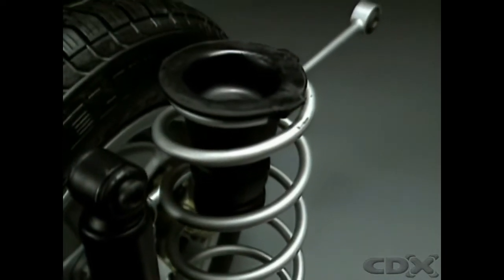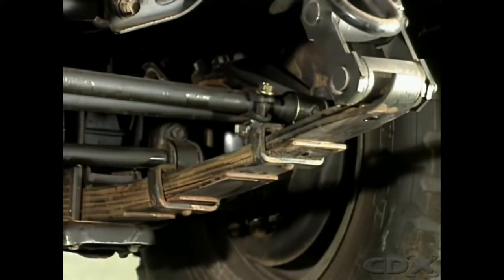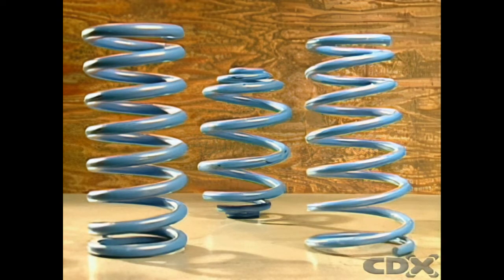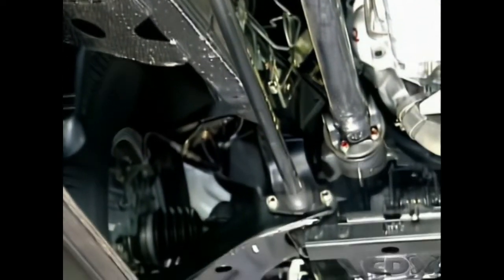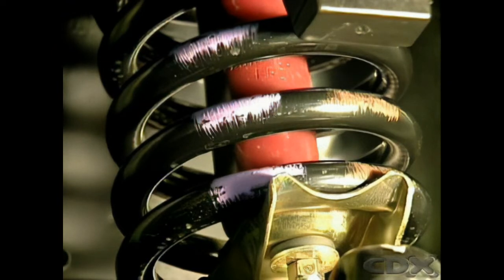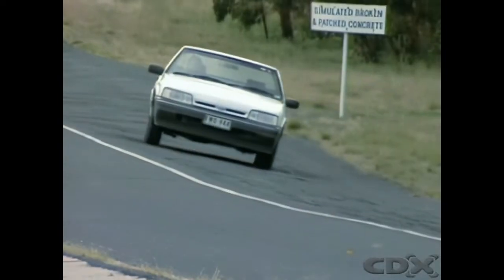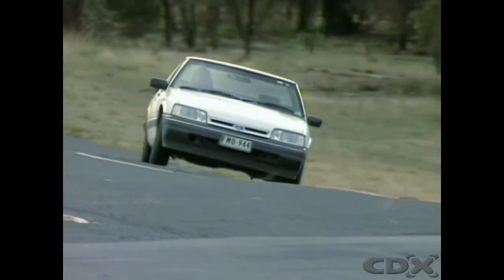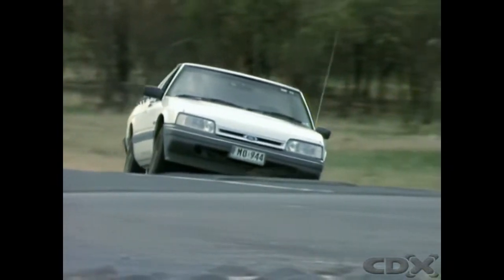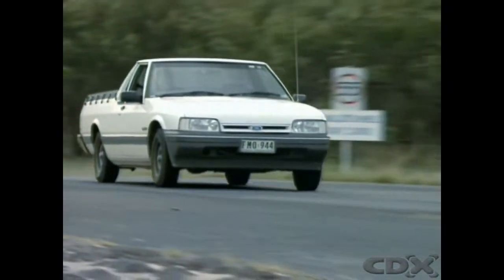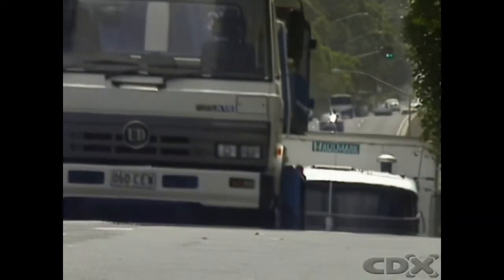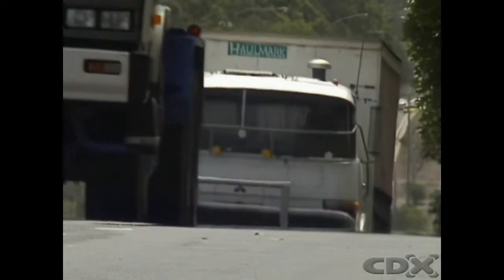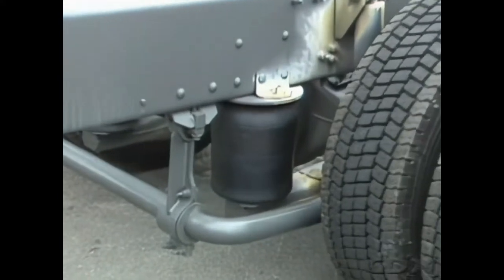The spring is the flexible component of the suspension. Basic types are leaf springs, coil springs, and torsion bars. Modern passenger vehicles usually use light coil springs. Light commercial vehicles have heavier springs than passenger vehicles and can have coil springs at the front and leaf springs at the rear. Heavy commercial vehicles usually use leaf springs or air suspension.